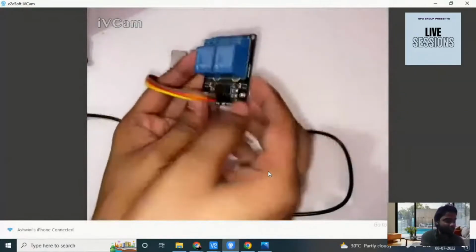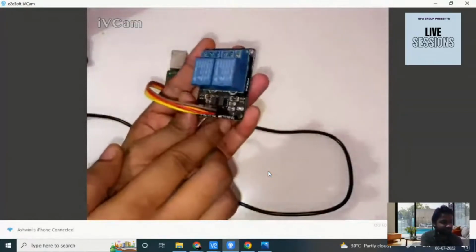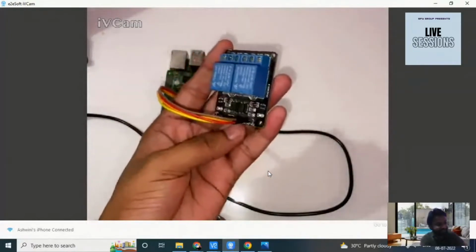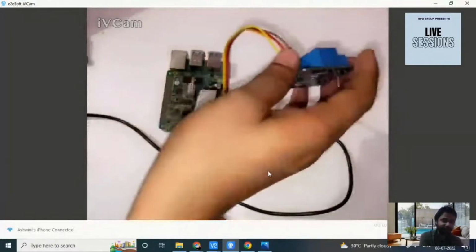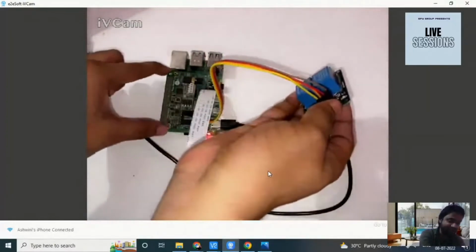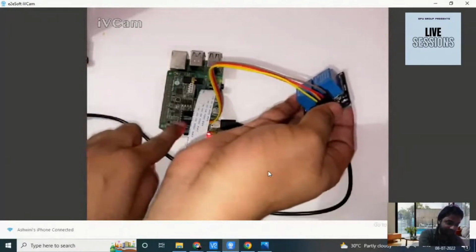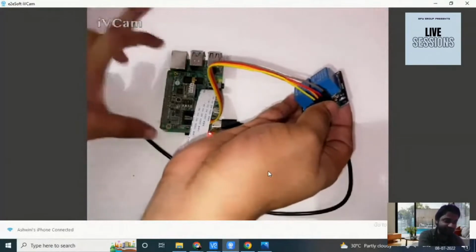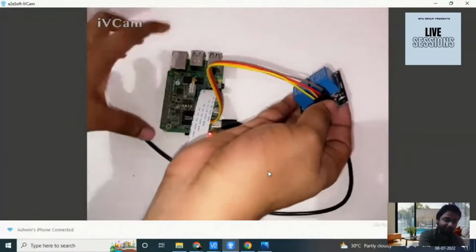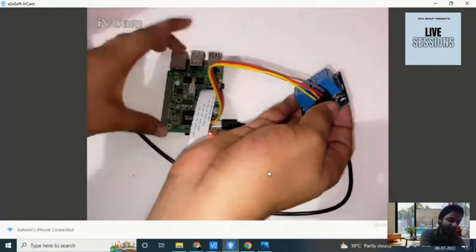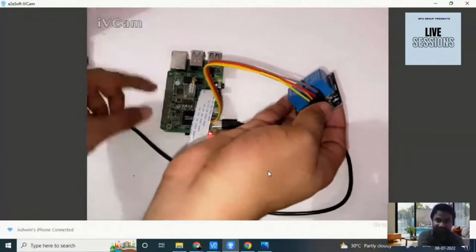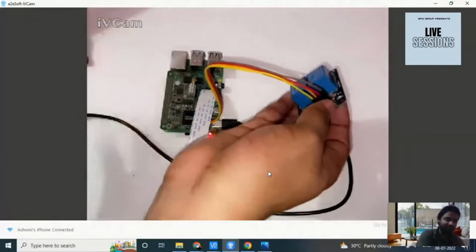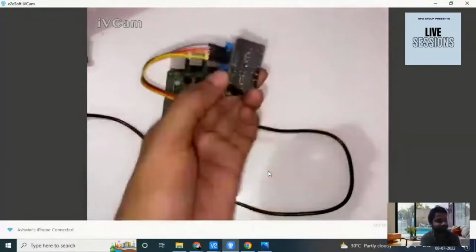And then you can see the various GPIO pins. This is an optocoupler relay, and these pins are connected with the GPIO of the RPI board. Here I have already attached a voice module, so I'm using the GPIO of this AI voice module, but this is not needed. You can change the pin number and use the GPIO of the Raspberry Pi or the default GPIO of the RPI board. But I have already attached it, and it is hard to get it out from the RPI board, so I leave it and use its GPIO pin.